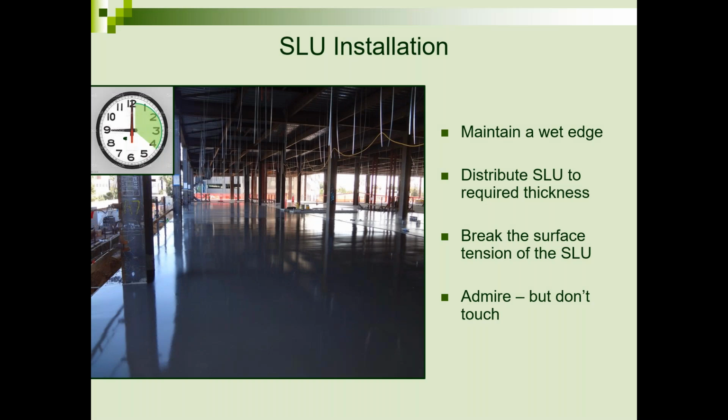And once you have that material placed, depending on the product, you've got maybe about 20 minutes after mixing to get that product placed, gauge raked, and paddled. And once you hit that 20-minute mark, or whatever the manufacturer tells you in the tech data sheet, you don't touch it again. Look in the background of this picture. The surface is dull, flat looking. It's lost its sheen. That product can't be touched again. You may be able to push your thumb into it, but you cannot manipulate it or work it with any type of tool, because that tooling will remain as a defect, a low point or potentially high point.